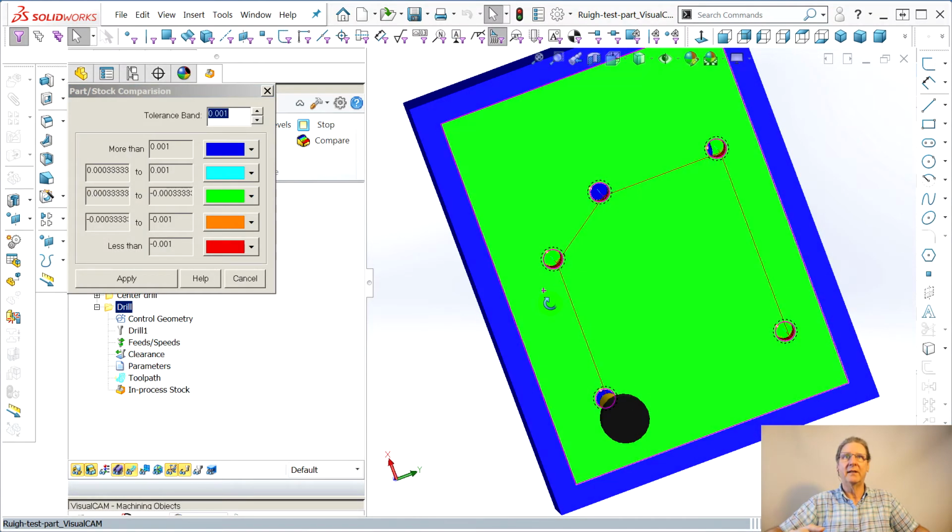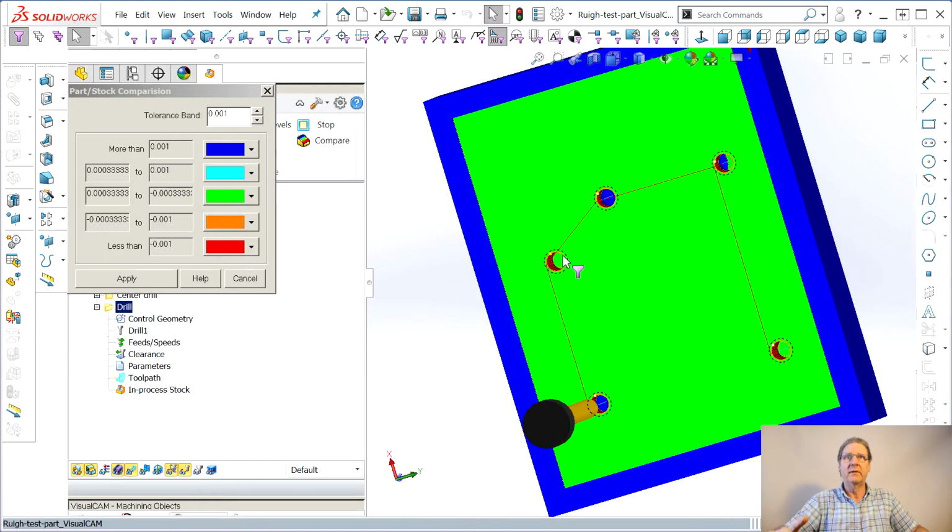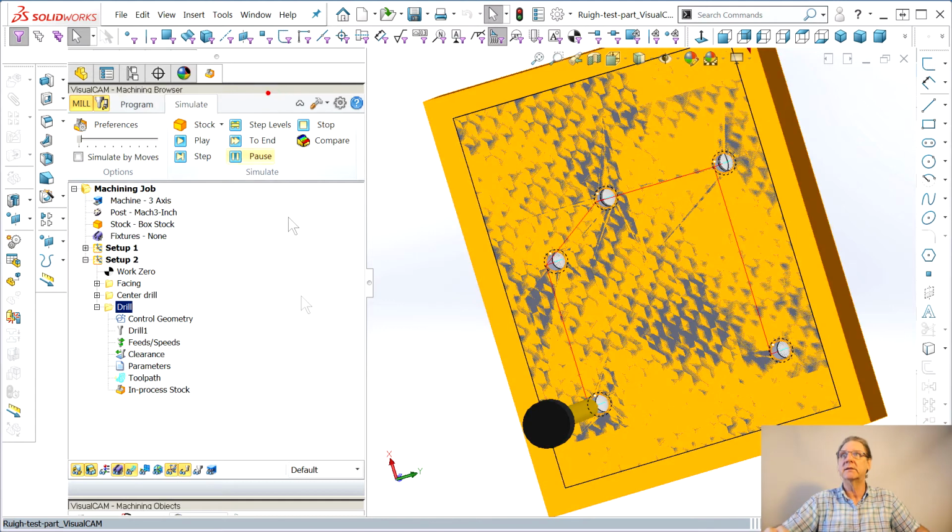See, they're all green. And that was tediously, maybe, well, 3.8 doesn't work. It's deeper. Maybe 4. No, not quite. 0.44. That's where it got so that the material that this drill thinks it removes. This is a serious problem, right? Who defines how, is it the shank? Is it the corner of the flute? Is it the tip of the drill? Everybody does it their own programmer herding cats ways.